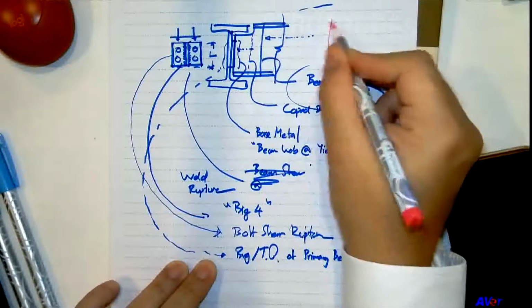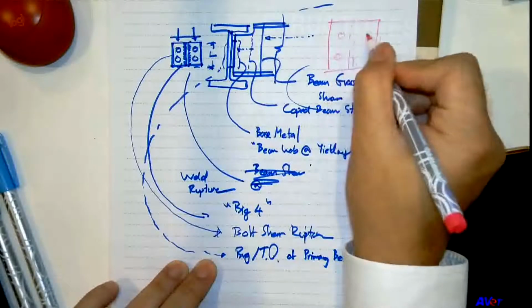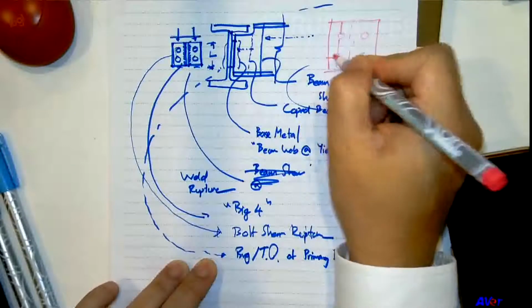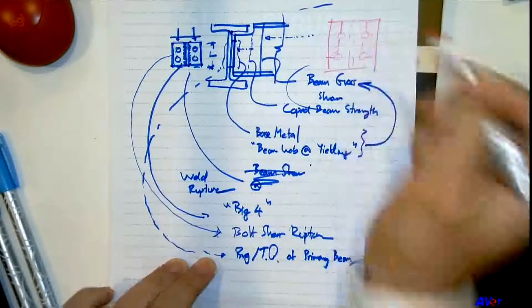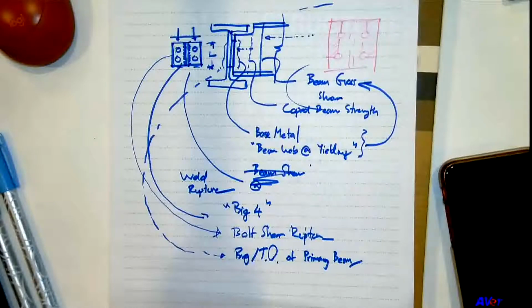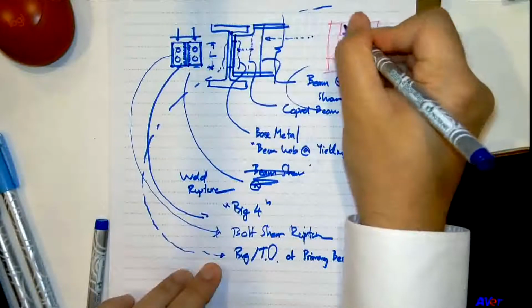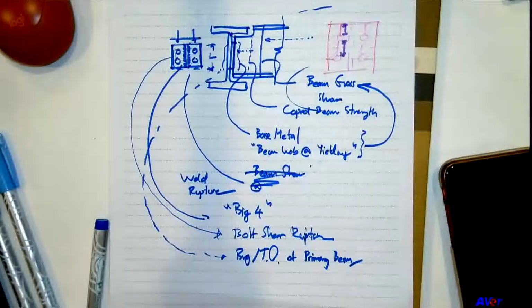Let me draw a bigger picture. For the block shear to occur and for the connection to fall down, this is where the block shear is going to occur, right? And then you have the bearing tear out of these four holes, which, this is the Lc of that bolt hole, and that is the Lc of the internal bolt hole, right?